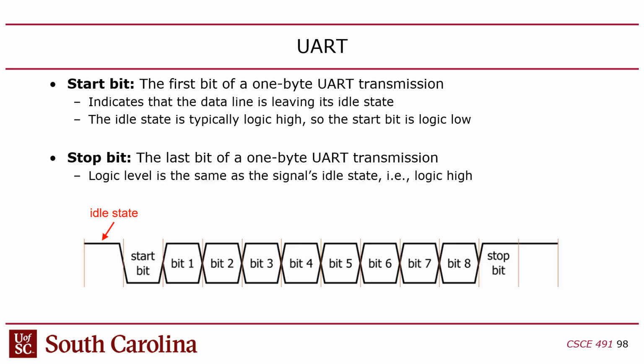The problem with that is that it doesn't make any guarantees about the phase. It's only talking about the bit time. So the issue with UART is that I know how much time is set aside for each bit on the receiving end, but I don't know when the transmitter is changing those bits. I don't know when I'm supposed to sample it, which inevitably causes errors. There's just no way around it. You're going to get errors. So keep that in mind.